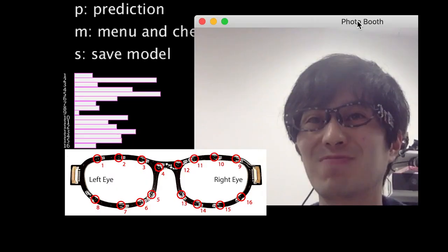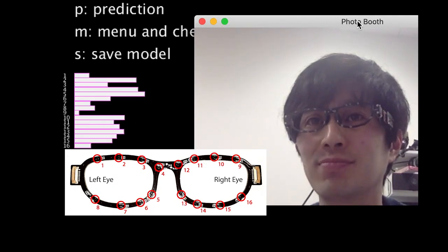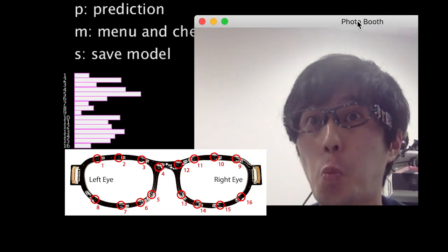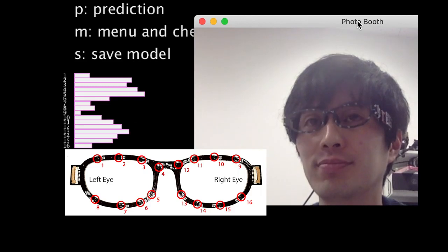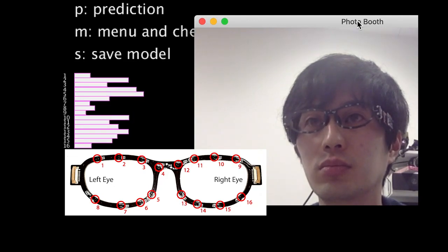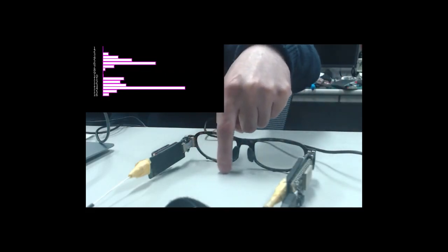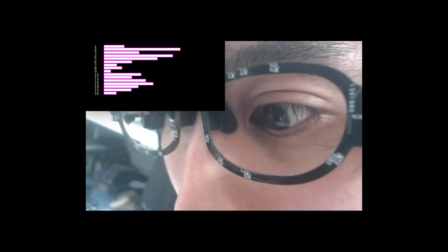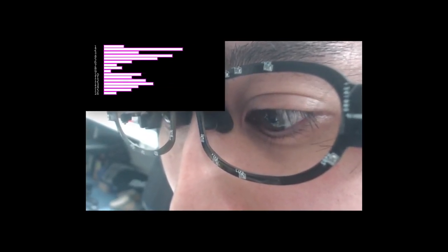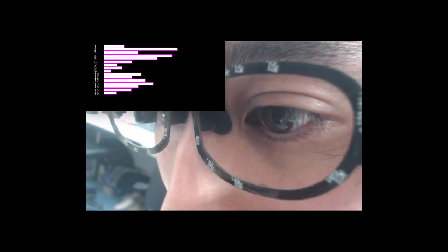We used 16 optical sensors which measure the skin deformation through reflective intensity. Depending on facial expression states, the sensor values change. Also, the eye movement makes skin deformations, which change the sensor values as well. The sensor works like proximity sensors, and the eyeball movement changes the shape of the skin and the eyelids. This changes the distance between the sensors and the skin surface.